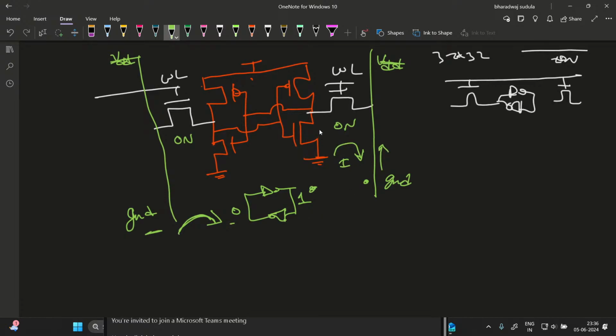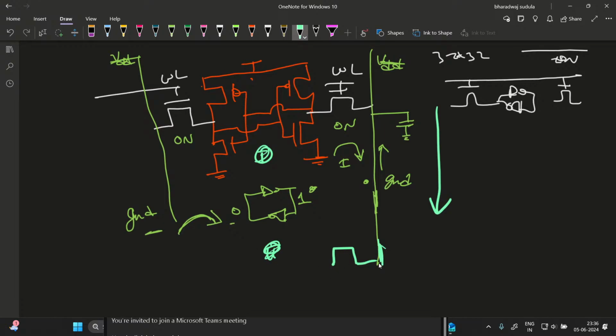So this bit line, every wire has some capacitance. Not only that wire capacitance, you even have a column of cells. In this column, you have a cell underneath this SRAM cell, another cell here. So this column bit line will be connected to another word line transistor, so this diffusion capacitance is also there.